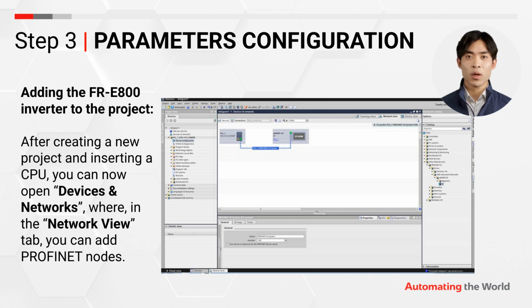The second step involves adding the inverter to the project. After creating a new project and inserting the CPU, you can open Device and Networks. Here, in this Network View tab, you can add Profinet nodes. You need to select the node linked to the FR-E and drag it into the project.